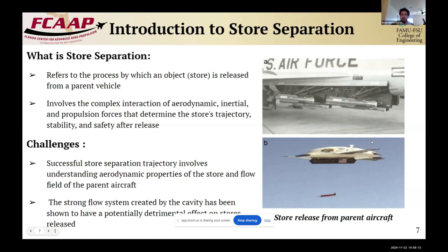And this helps, namely by number one, reducing drag. That's easy. And secondly, it increases the safety of that store during the flight phases, as it's not subjected to the outside flow conditions, making it safer for the pilot. Now, what are the challenges here? Well, successful store separation involves understanding all of these properties and forces surrounding the store and cavity flow system.